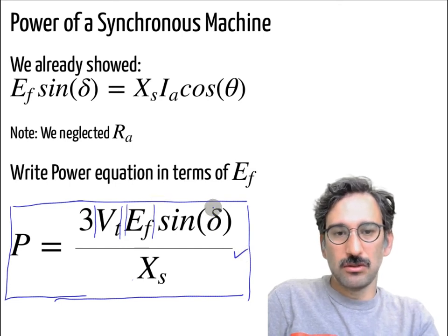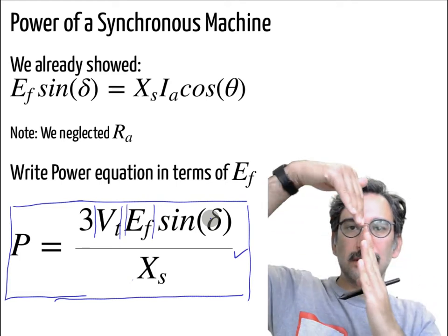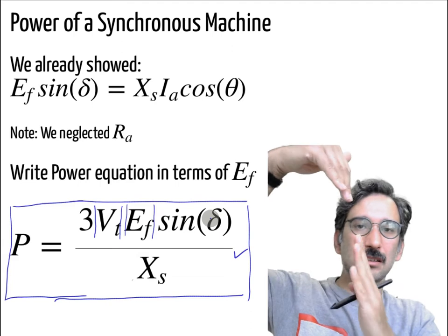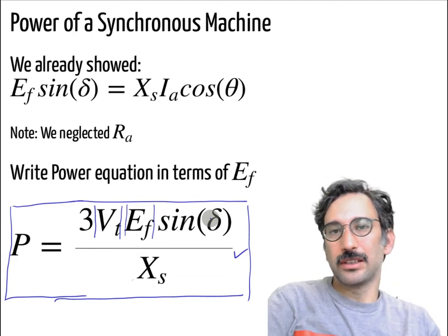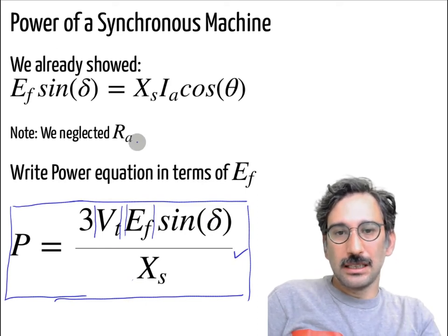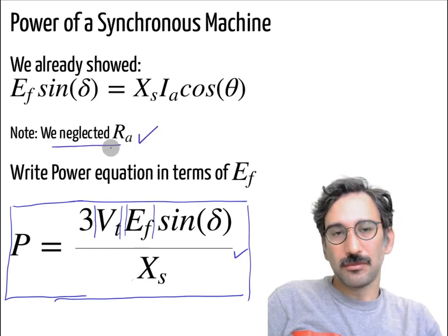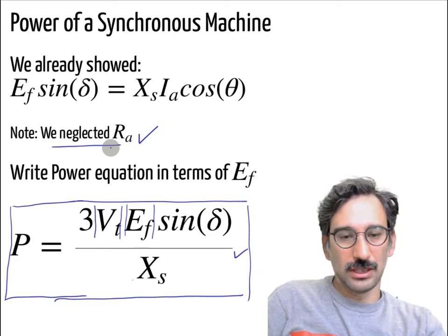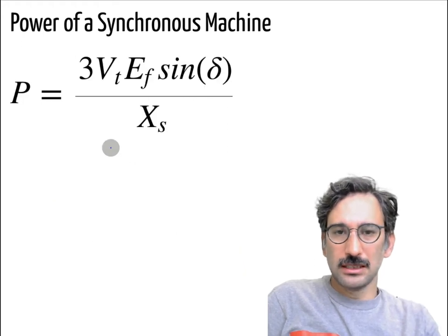You can see that if there is no load angle, meaning the rotor and stator MMF are aligned, the load angle is 0, and in that case we are not generating any force or any torque, therefore we are not consuming any power. Another important thing, which we will see in the following weeks, is that in this equation we neglected the I squared R losses in the machine, so it is like a 100% efficiency machine. So this is the power.